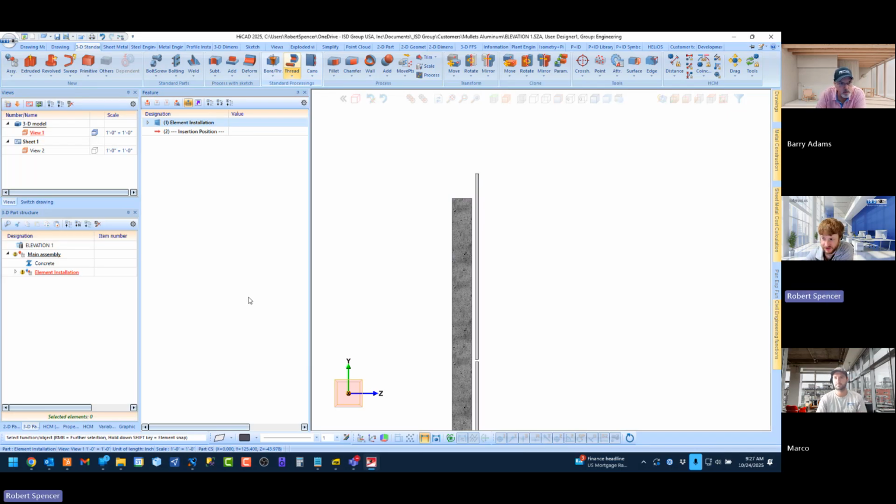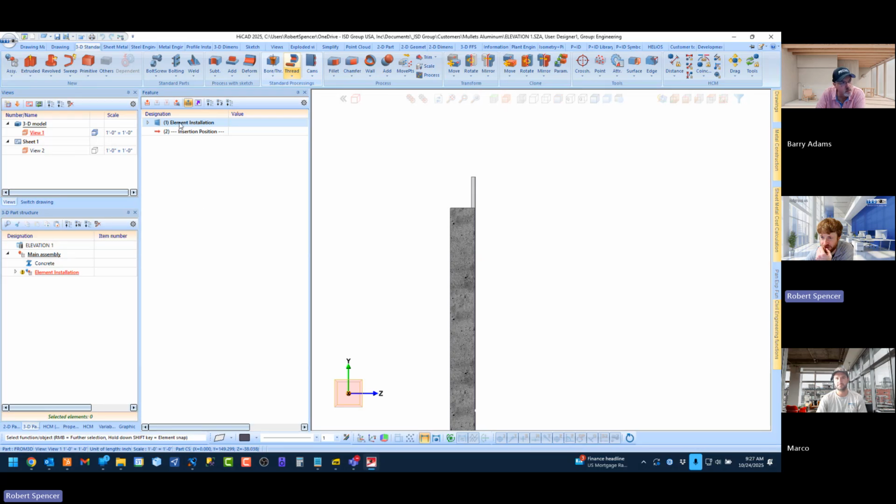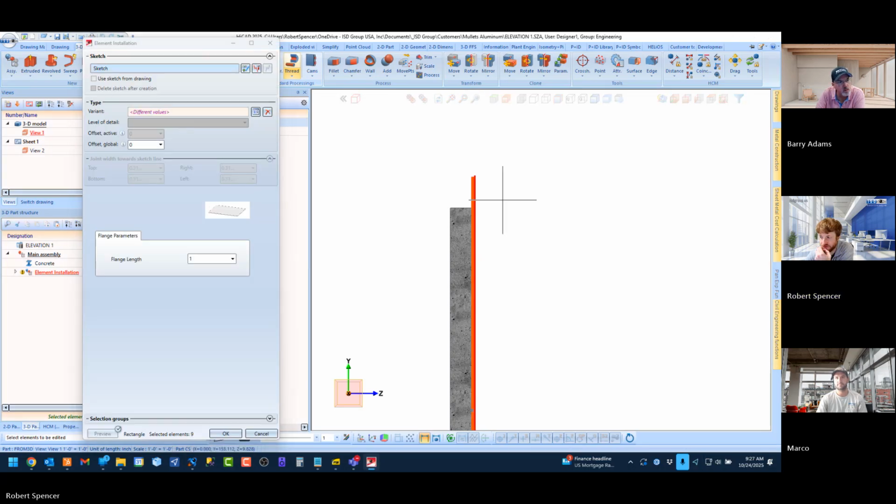Well, there's multiple ways, but I usually put it flush on the building. And here, I'm going to fix that in a minute, so that I can use these offsets. Because you can always sit here and play around. Now, a reason for why you might move the assembly is say you modeled some substructure behind it, and you don't exactly know what the exact value you need. Well, then you might just do a transform from a surface to a surface. That might be easier than trying to figure out what the magical number is to type it in.